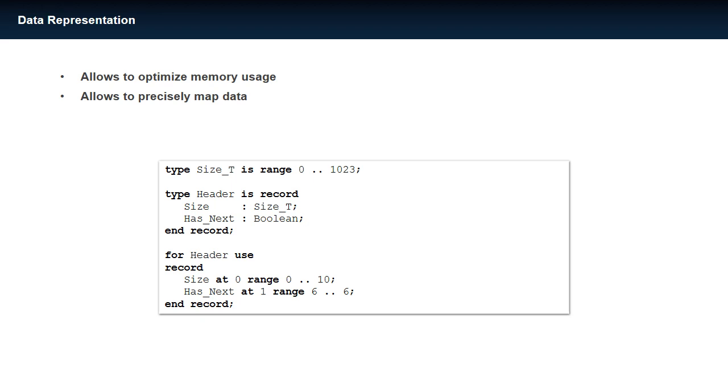The compiler will guarantee this memory layout and its consistency by looking for overlapping types at compile time. At runtime, it will insert all of the necessary masking and bit shifting in order to actually manipulate and access specific bytes and specific bits. For embedded bare metal work, this is incredibly useful because many mistakes happen when developers are using many bit shifts and logical statements to access sets of bits.